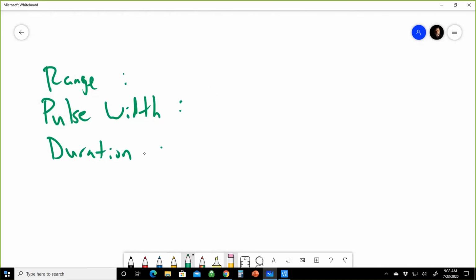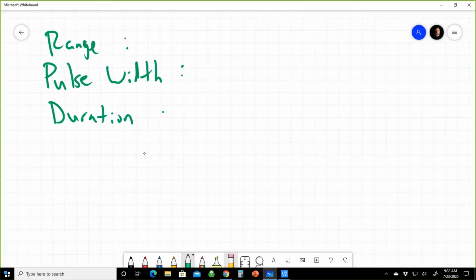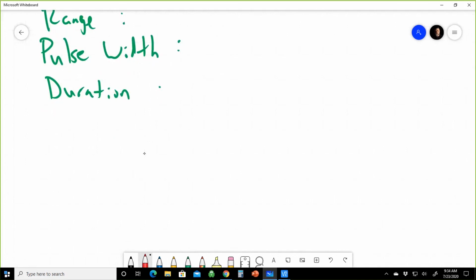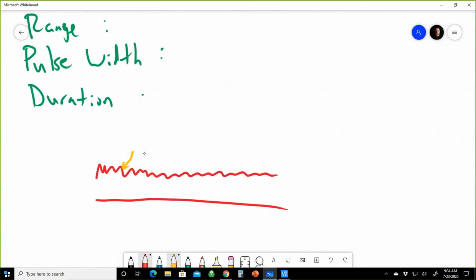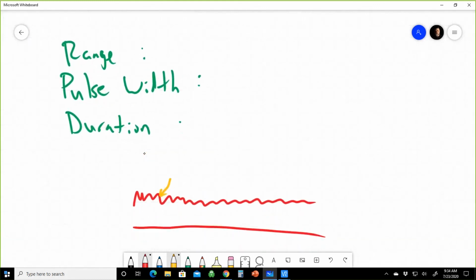But the problem with very short pulse widths is you contribute noise to the trace. So if you have 0.05 dB splice losses and stuff like that, they may get hidden in the noise of the OTDR trace. Because you have this OTDR trace at 5 nanoseconds, if you zoom in, it might look like this. At 100 nanoseconds, it'll look like this. And so we will lose a low loss splice inside of these valleys. But do you really care about a splice loss that low? Or are you looking for more higher contributing stuff?